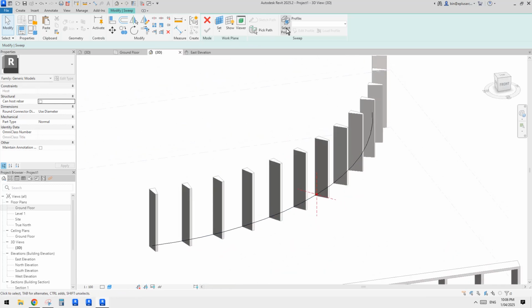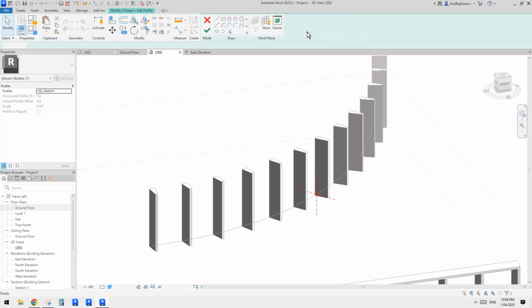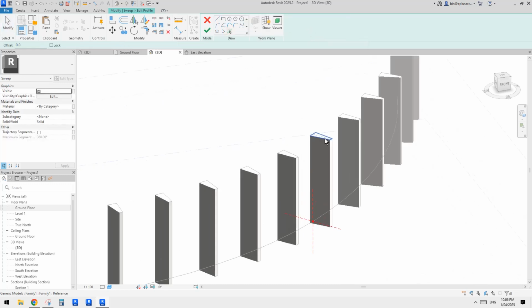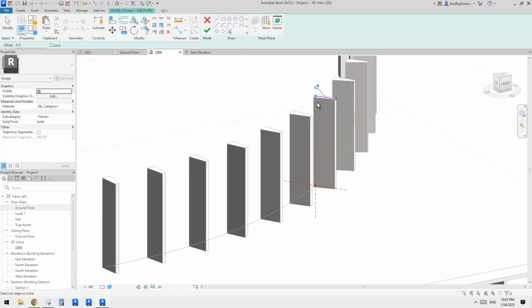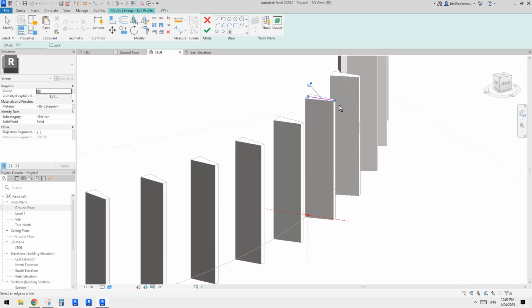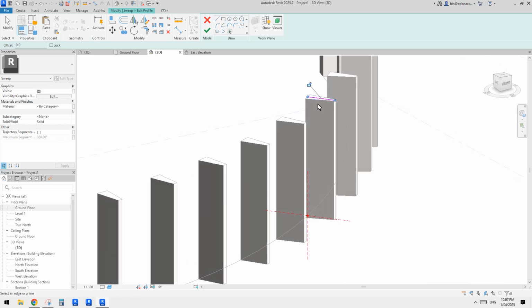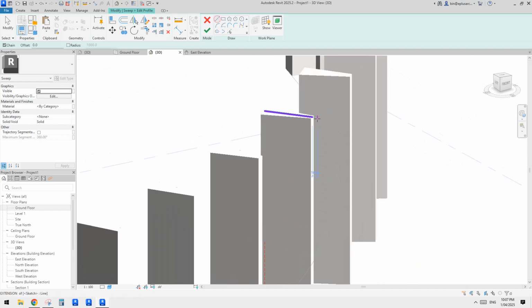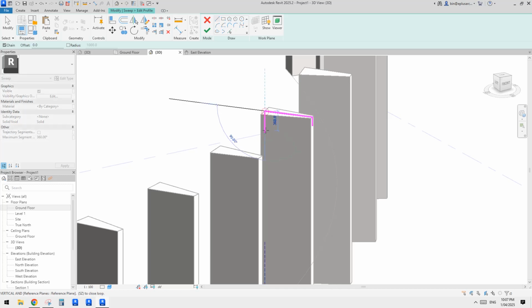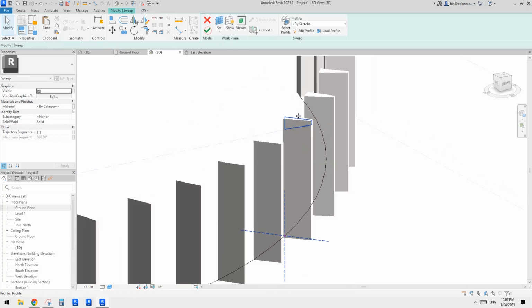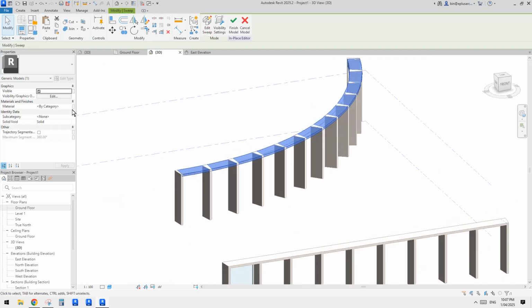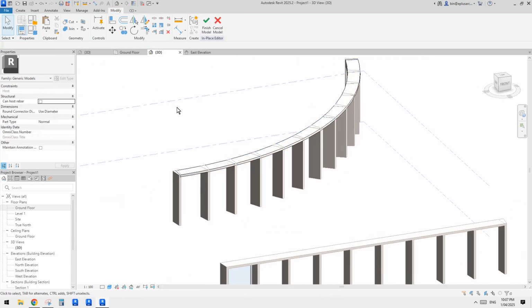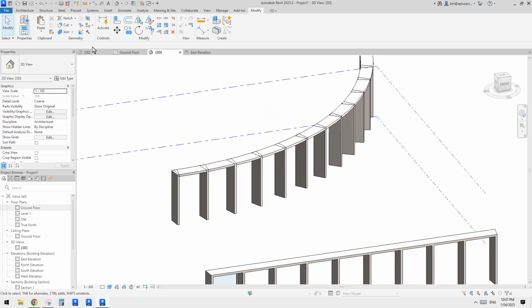Okay, it's roughly in the center, so probably I can just use this one. So let's just select profile and then edit profile and pick. We can just pick this one. I think this should be close enough, right? We know roughly the width of this one, and then we just draw a line from here down by 150, same as the last one. So this 400, and that's it. Okay, so now finish this, and then we have this, and then also just use the same material and finish. Now we just need to join them.